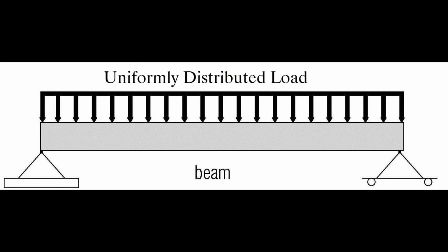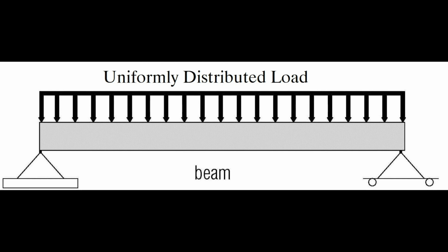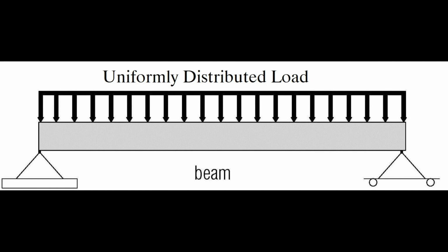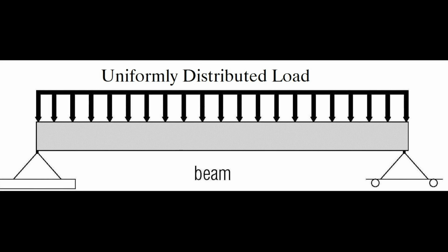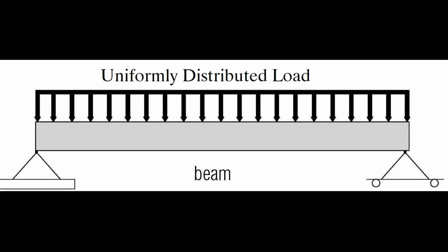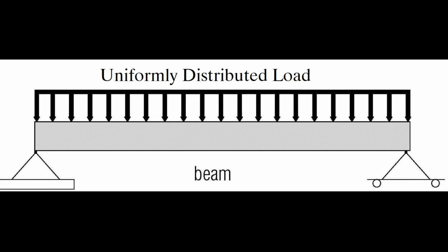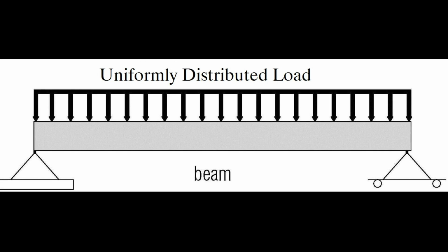Hello, my name is Marcel, and I will be discussing phase 2 of our project, which is the load analysis. This includes the dead loads, live loads, and the reaction forces of our bridge. In order to find the live load, we had to find the pressure, which is stated in the Australian standard 1170.1, which gave us a pressure of 5.0 kPa. This was used to find the live load as we multiplied it by the area of the bridge, which was 5.74 meters.